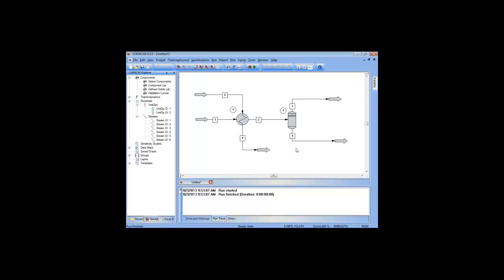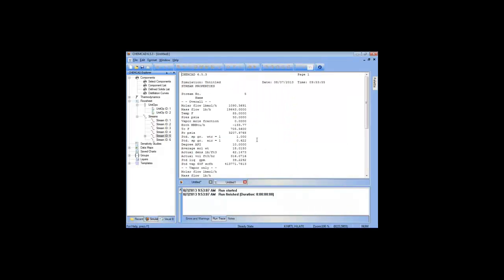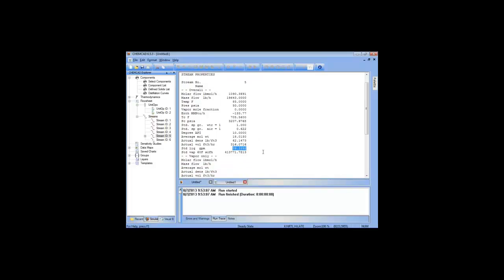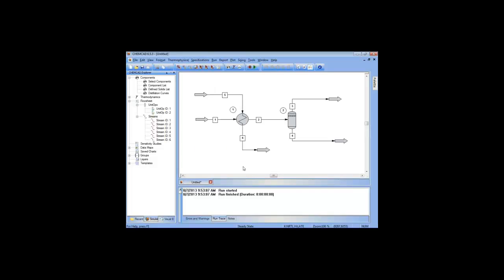So now we've set up a simulation. We've solved some problem. We had a mixture that was a little hot. We cooled it down. We needed to cool to 250. The question was, how much water do we use? We can come in here and do View Properties, Standard Liquids, gallons. So we need 39 gallons per minute to do so.